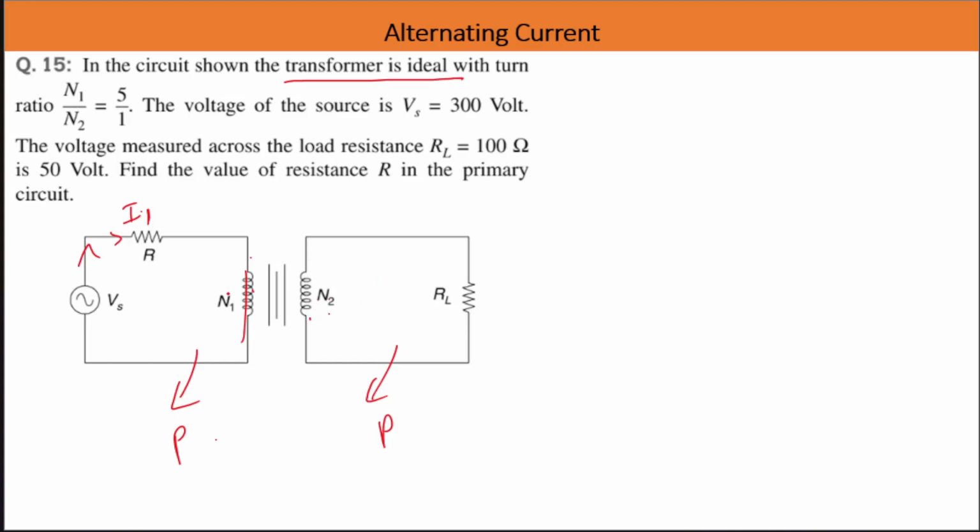and because of flux changing here, flux also will change here, and here voltage will get induced, and the induced voltage will induce current in this secondary circuit. This is the secondary circuit, okay. And since this is the induced current in the secondary circuit, its direction will be opposite to that of the current in the primary circuit, according to Lenz's law. So current will be like this.